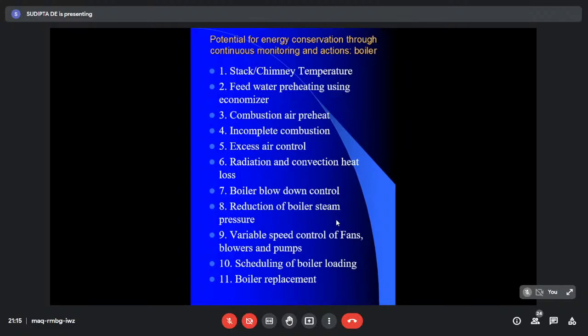How you can avoid it in an industrial system is not possible to discuss here. There are different mechanisms, such as mixing different boiler streams and then combining them into a common final feeder line. So these are the options possible. But I'm giving you the idea that an increase in boiler steam pressure means a drastic reduction of its efficiency. So go for lower pressure operation. If required, you can manage the system, but how it will be done, I'm not going to discuss like other points.